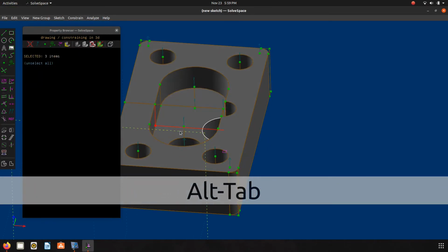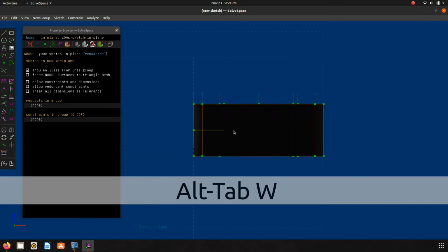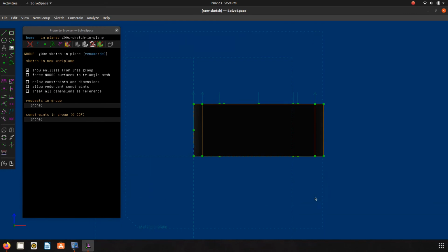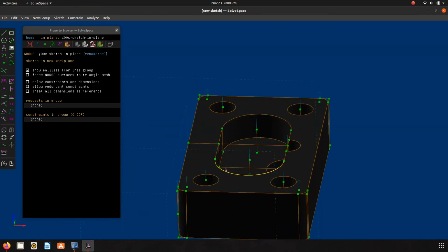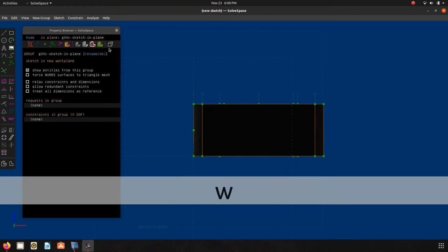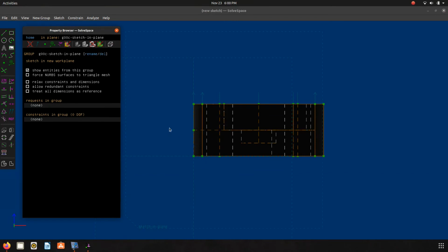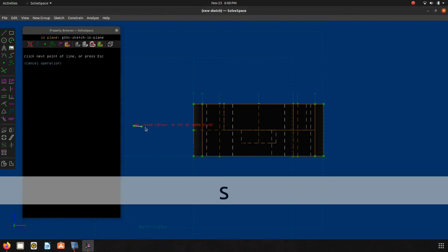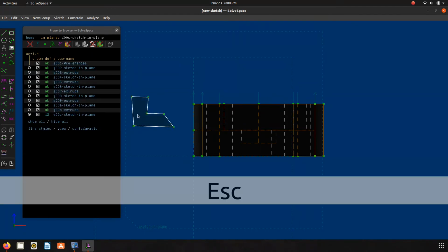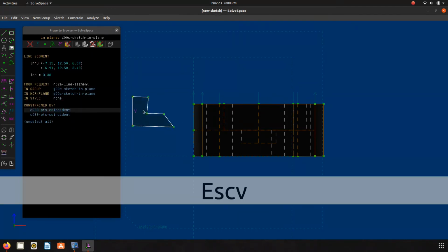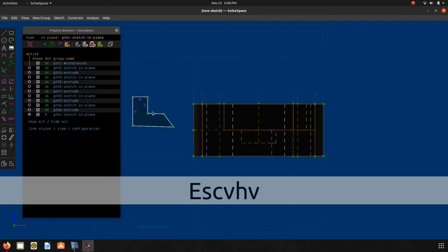So moving on, we can go in and put in this feature here, and I want to do a full model of this part, not anything cheating. So what I'll do is sketch on this, after I said I was going to cheat this whole time, I know. I'm going to sketch on that work plane, a mid plane on this part, by selecting a line, point, line. And then I'm going to turn on hidden lines. Now, this might make it kind of confusing or difficult to fully understand, but I've found that it's pretty easy to just rough out the shape that you want outside the feature. And we'll make these vertical, horizontal, vertical,